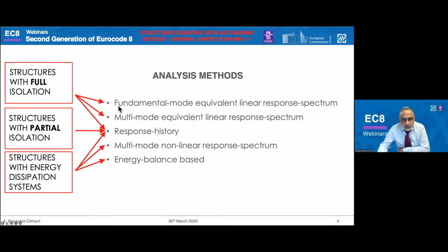The fundamental mode equivalent linear response spectrum and the multi-mode equivalent linear response spectrum are used in structures with full isolation. And finally, the multi-mode nonlinear response spectrum and the energy balance-based analysis is used for structures with energy dissipation systems.